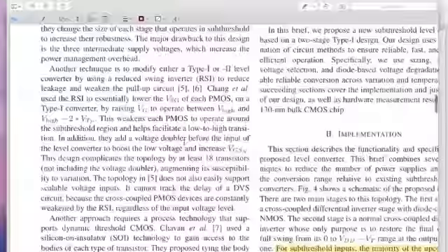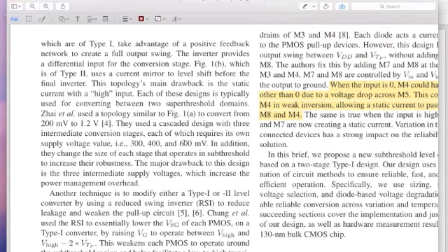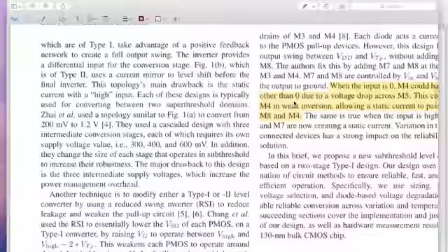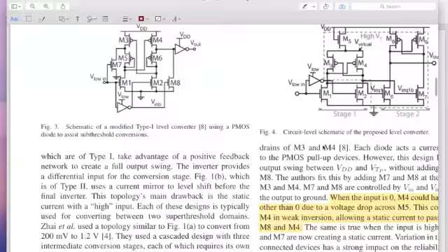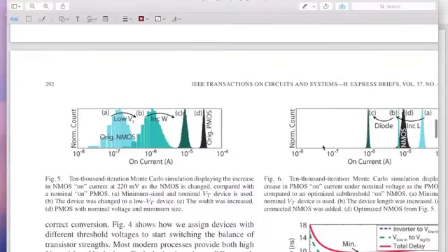So another technique is also, the question which is being asked is, can we use body bias to somehow modulate that? And body bias is also another technique where you can use the body bias for the M3 and M4, because finally you want to strengthen the pull down NMOSes and weaken the pull up PMOSes somehow. So all possible ways you can explore, and if you have the knobs to adjust body bias, that would be another way to adjust that. If the normal potential is low VT device and high VT for PMOS. Correct. So the question is, just low VT by itself doesn't it suffice?